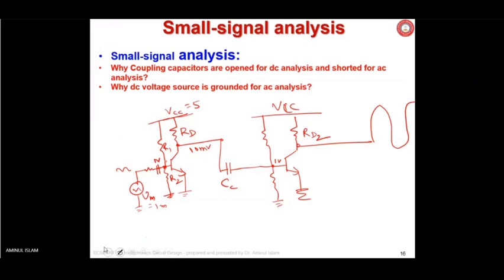This point should be isolated from this point. Voltage here and there are different for proper biasing. Proper biasing means, remember, base emitter forward bias and base collector reverse bias. That may not be possible if directly connected sometimes. So in that case, connect a coupling capacitor. This is the coupling capacitor, coupling between two amplifier stages, output of one connected to the input of the next stage. Could you understand what a coupling capacitor is? Harsh Tripathi?